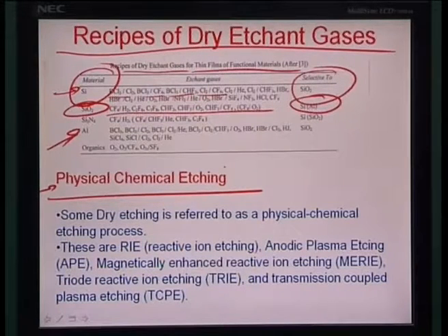So, these are called reactive ion etchers, or the reactive ion etching process, and it depends on the pressure zone in which a plasma has to be created over a surface. Essentially there is a chemical gas phase reaction which is responsible for etching, but it is done within a plasma atmosphere where there are ions and electrons of this gas, and there is a certain drive pressure or ionic momentum which is imparted to these species. It can drive into a substrate and start removing material from the substrate.